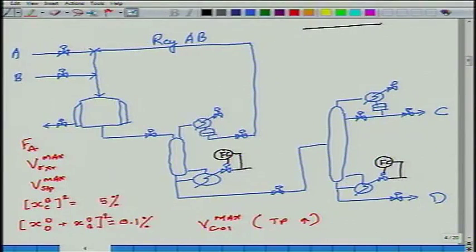See, my constraint value on boil up is this. If I am using the boil up for controlling something, whether it is a level or a column tray temperature, what that means is boil up will have to move to control the tray temperature, right? It cannot be constant, because feed composition is changing, there are disturbances coming, the boiler pressure is changing, and the temperature of the feed to the column is changing. That being the case, my boil up is varying.